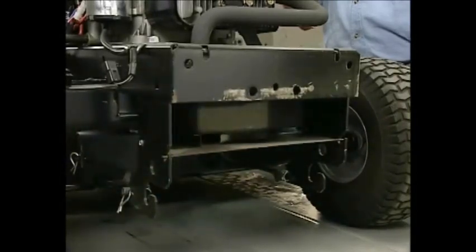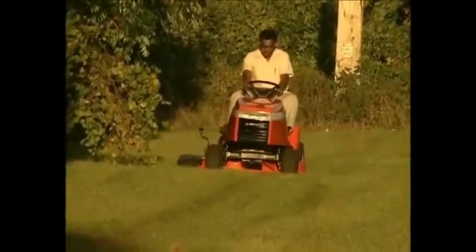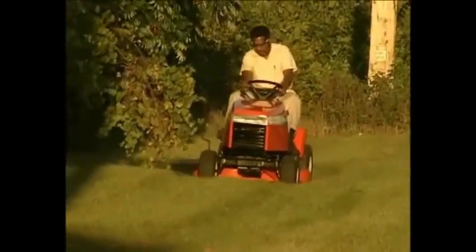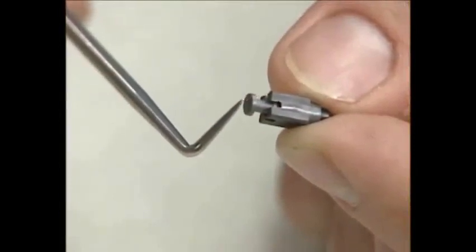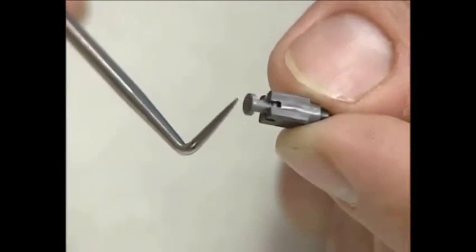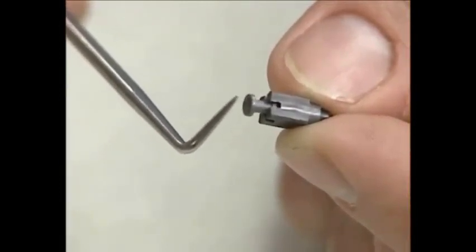We've even seen twin-cylinder engines that have been run for months, if not years, on one cylinder, resulting in oil dilution failures. A bouncing float can also occur with a running engine. If the equipment is running over rough terrain, the float will bounce. Some fuel inlet needles are designed to compensate for this situation. The needles have small springs on the back where they make contact with the float. These small springs act like small shock absorbers.